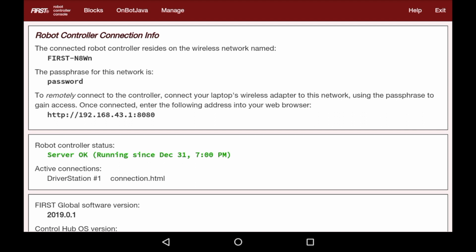A few basic concepts: each motor comes with an encoder built in, which is essentially a rotation sensor. And this is the second wire, not the red and black one, that connects up to your control hub. It's the JST-PH4 pin wire. So, every time you turn off and turn on your control hub, your encoder count starts off at 0.